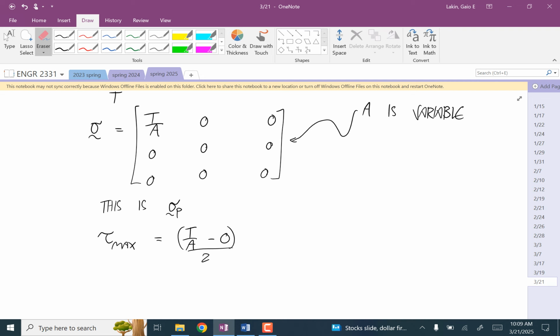But once you choose an x location, there's no change due to tension and compression as you move along the cross section. But with bending, it does change as you move up and down on the cross section. With shear force, it's going to change as you go up and down on the cross section. And when we talk about torsion, it'll actually change in every direction along the cross section.